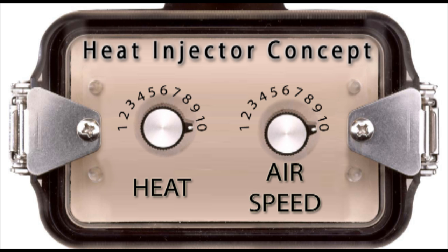With the heat injector system, the operator can reduce the air volume by as much as 70% during the times when painting isn't taking place, and any reduction in the volume of fresh air that needs to be heated produces a direct savings in gas consumption. For a typical automotive refinish booth, the airspeed could be reduced during prep, flash, and cure.